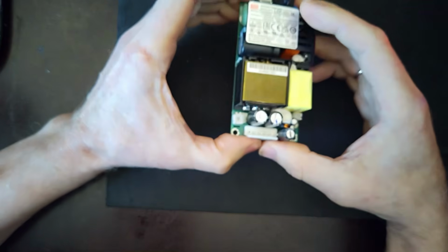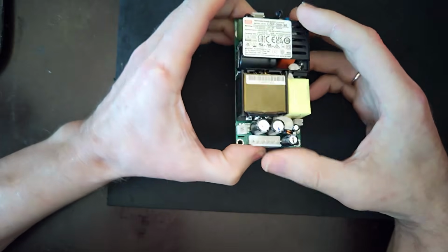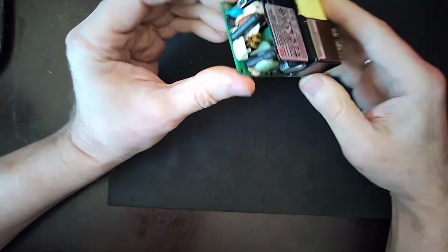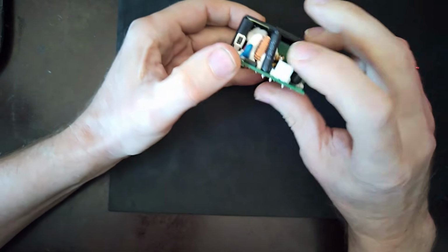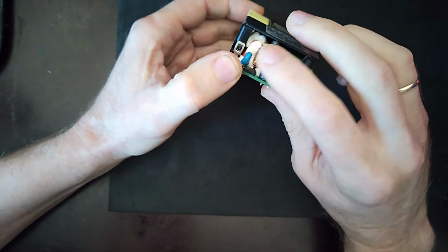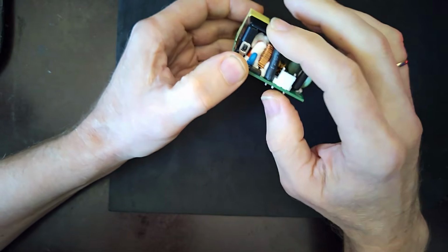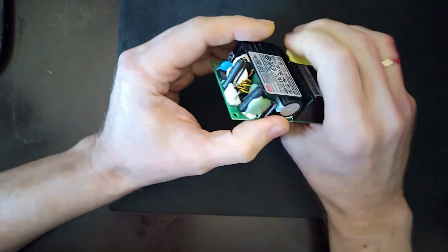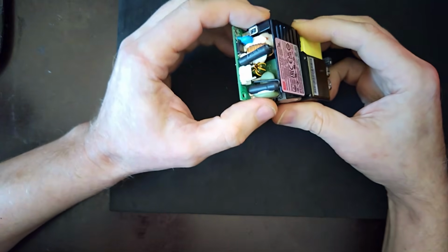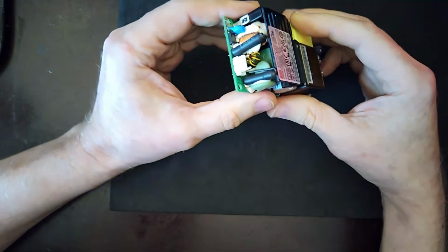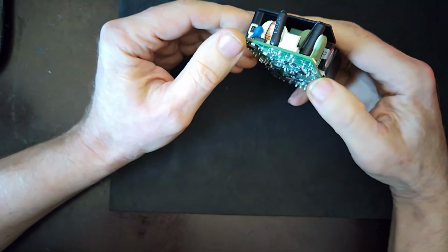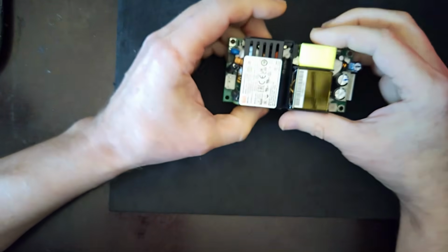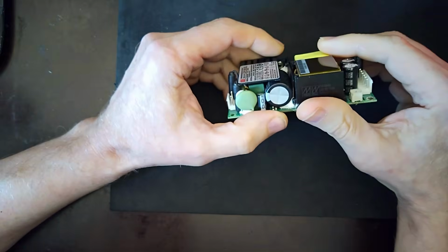You don't even need additional large capacitors. You can drive boards with small capacitors on board. There are some boards where you are saving on the capacitors. Very good. Also for your safety, there are two melting fuses and surge protection. You can use it for medical. If something happens with this power supply, then those blow up and there is no voltage on the chassis, so you will not get any problems with that. And with low leakage, it is allowed to use in medical equipment as well.